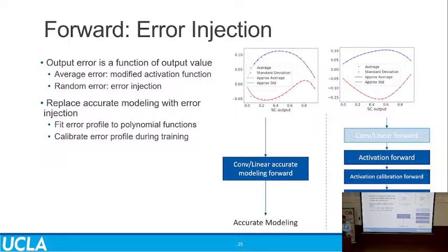What are some of the ways in which random number generation works? What are some of the algorithms that are used? So the most common digital algorithm is the linear feedback shift register. You just have a linear feedback shift register that generates pseudo-random numbers. That's a very standard way. It's a small little digital block. Of course, if you want randomness guarantees, there are a whole slew of other random number generators which try to leverage some stochastic noise in the underlying hardware. And there are lots of them.